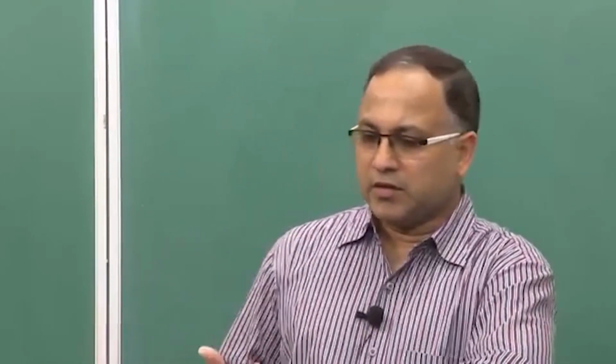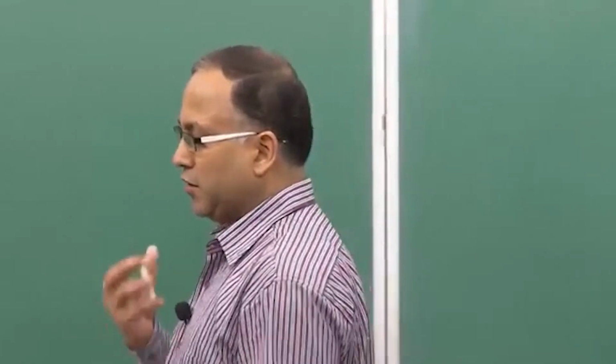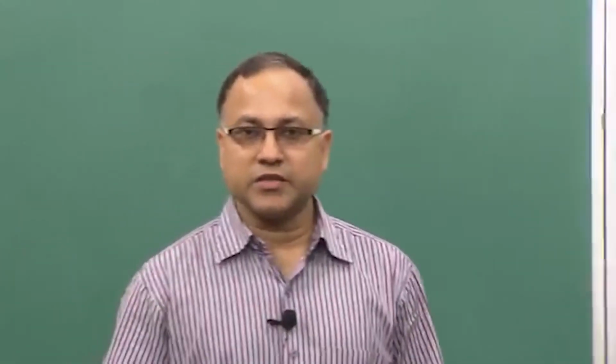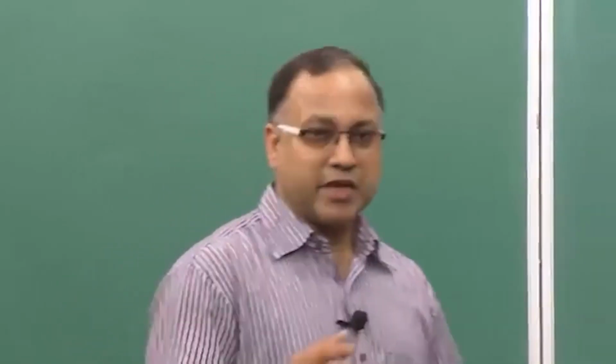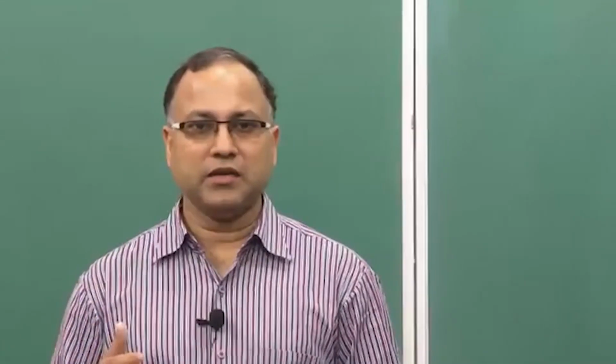Welcome back to the course Mechanics of Solids. In the last lecture we were talking about the stresses. We defined the normal stress and the shear stress, and we have seen that if you want to define the state of stress at a particular point, you need 9 stress components in the 3-dimensional state of stress. Now, in most of the mechanics problems we will be dealing with in this course, we will be taking care of the 2-dimensional state of stress.